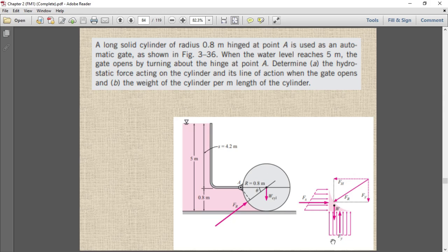So here you can see the pressure distribution on this curved surface. You see the curve is not holding any fluid. The curve which is holding the fluid exerts a force on the fluid. So what is the force acting downward, or what is the fluid which is acting downward? You can see this is the curve, and here is the fluid pressure distribution. This is our curved surface, and I take the projection in the horizontal direction and the projection in the vertical direction.